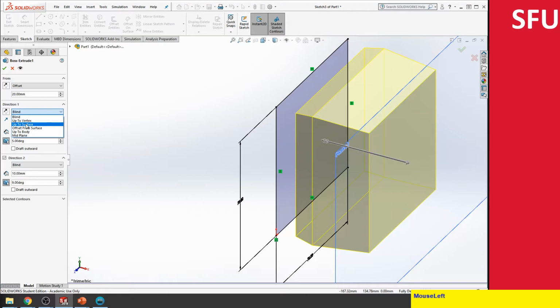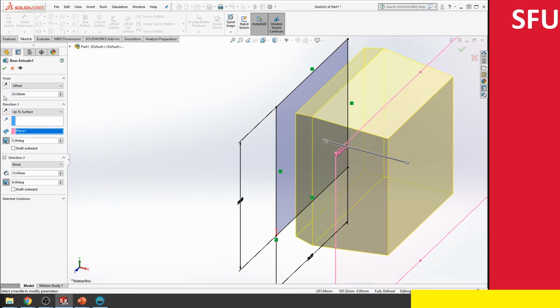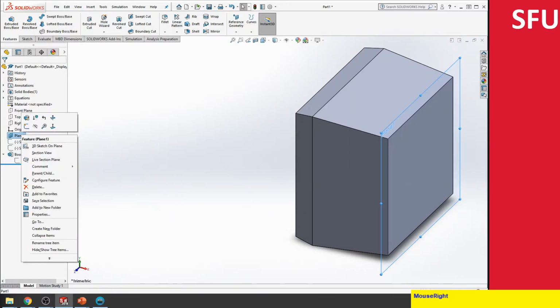So now if I go back here and select edit feature, now instead of blind, I have the option of saying up to a vertex or up to a surface, and then I can select this surface, and based on the distance, it gets updated over here. As before, if I wanted to change the geometry, like the cross section, I can do it on the sketch, but this is basically being controlled by plane 1.